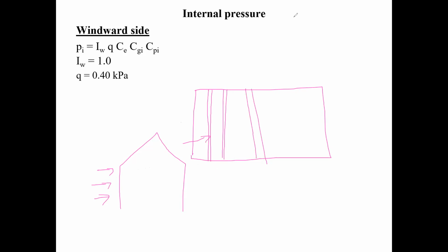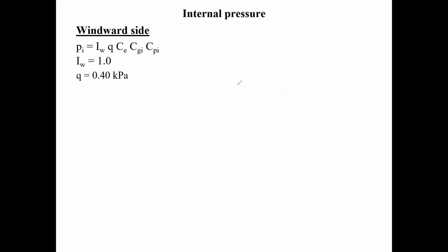Yeah, I got it. So you look at it as a whole structure. Exactly. Now I'm looking at a whole structure. So for example, in plan view, when we're going to be doing the steel, we're going to be doing the wind loads. Well, we're going to be using the same figure that we use for structural analysis. Why? Because now we're going to be designing the system for the primary structure. In other words, how the building is going to hold together.